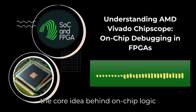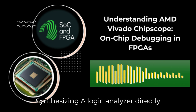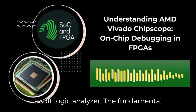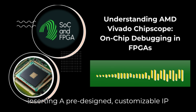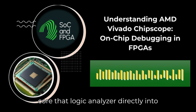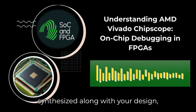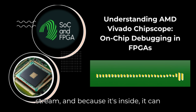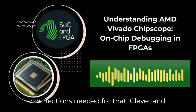That really is the core idea behind on-chip logic analysis. You're effectively synthesizing a logic analyzer directly inside the FPGA fabric. Think of it like a soft logic analyzer. Okay. The fundamental principle is instrumentation. This means inserting a pre-designed, customizable logic analyzer IP core directly into your design's netlist. It gets synthesized along with your design, becomes an integral part of the final bitstream, and because it's inside, it can access any internal signal. No external connections needed for that. Clever.